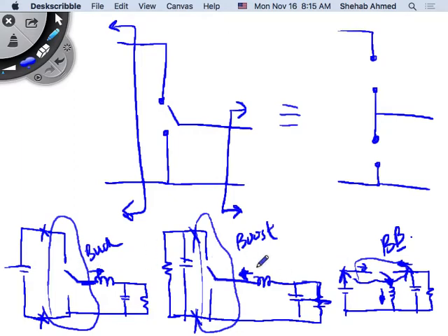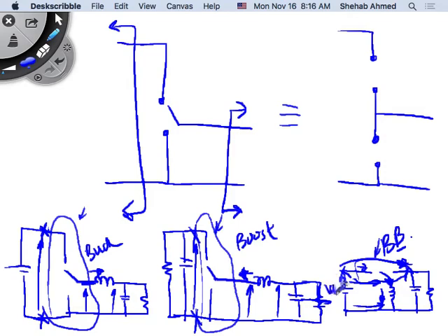So I just want to show that they're all very similar. They're all the same from that perspective. And one thing to note here: the voltage here and the voltage here, or after it's filtered, after the inductor, is the same as the voltage here and the voltage here and the voltage after the inductor after it's filtered. Meaning what? Meaning that these switches always see a stiff voltage across them, right? So these switches are seeing this VDC minus V output.